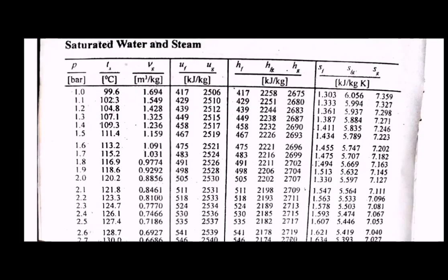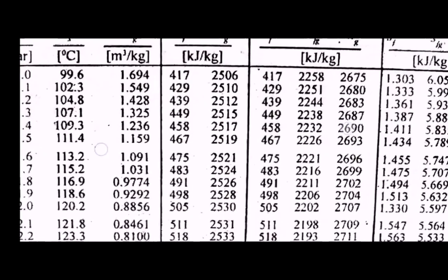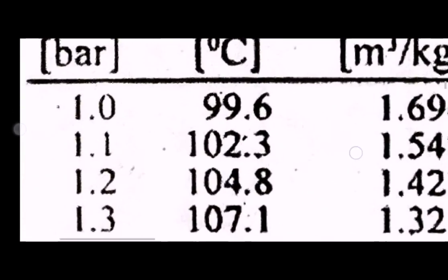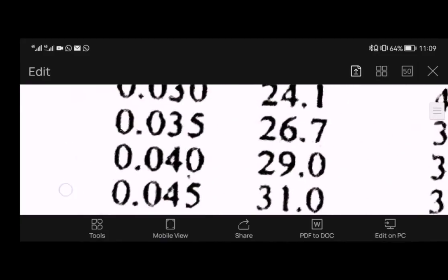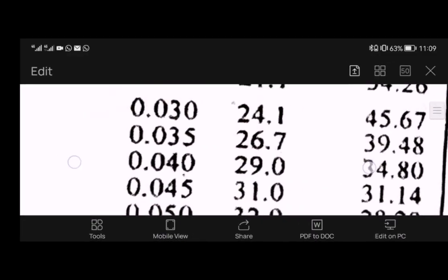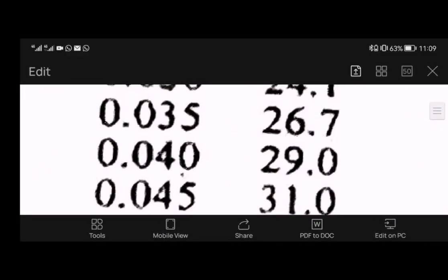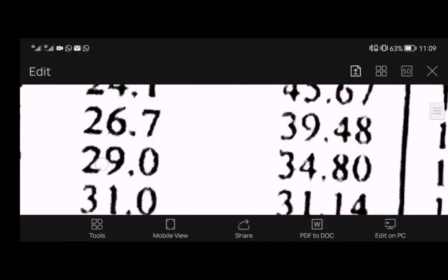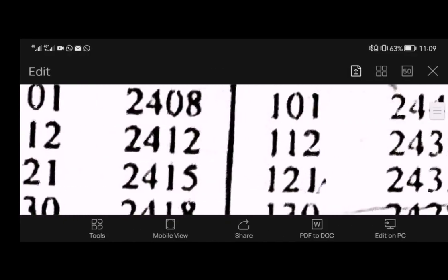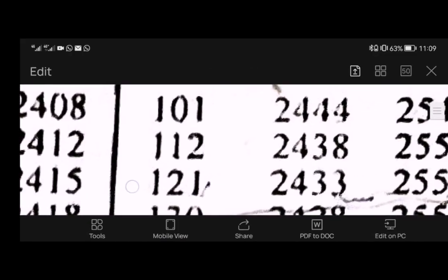So now we locate 0.04 bar. We go to the pressure. This is 1 point something, so it's quite high. Let's move up, so be careful. From the pressure, this is 0.40. We're looking for 0.04, right? Okay, so this is 0.04 bar here. This is the pressure line. So remember, you count 5: 1, 2, 3, 4, 5. So this is our HF, right?